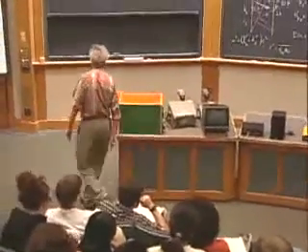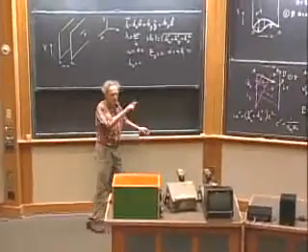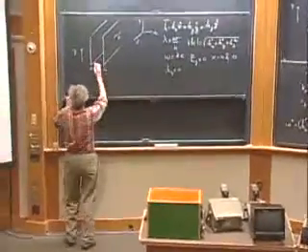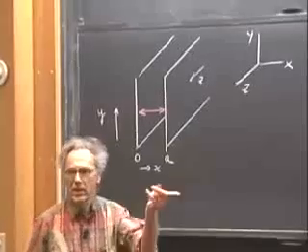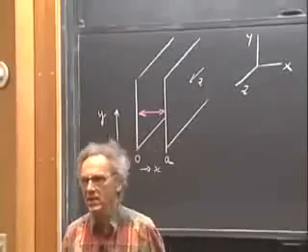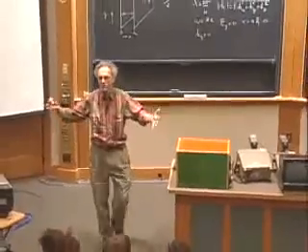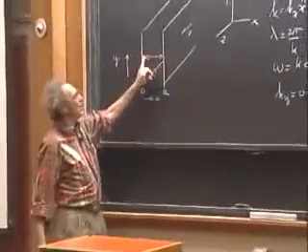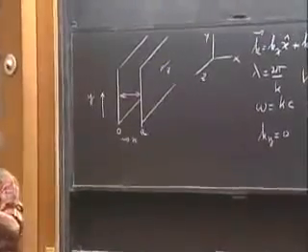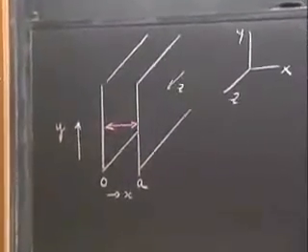If I rotate my transmitter by 90 degrees, and I will do that, believe me, and send in radiation whereby the E vector is linearly polarized in the x direction, there is no misery at all, because all boundary conditions will always be met by Mother Nature, because all that Mother Nature has to do is to make sure that the normal component at the conductor is sigma s divided by epsilon 0.